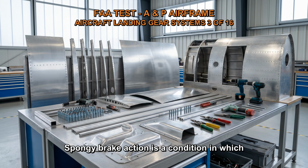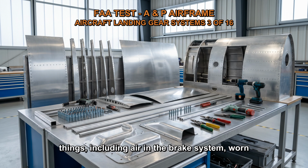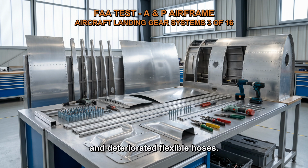Spongy brake action is a condition in which the brake pedal feels soft and does not provide a firm, solid feel. This can be caused by a number of things, including air in the brake system, worn brake linings, internal leakage in the master cylinder, and deteriorated flexible hoses. If it is determined that spongy brake action is not caused by air in the brake system, the next most likely cause is deteriorated flexible hoses.